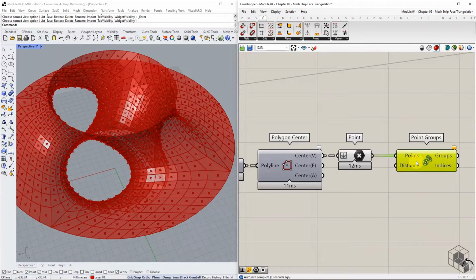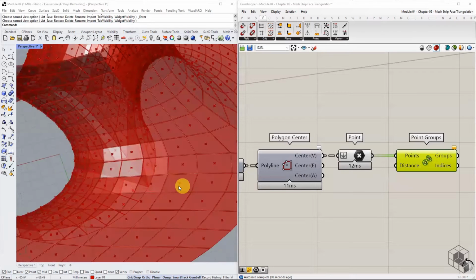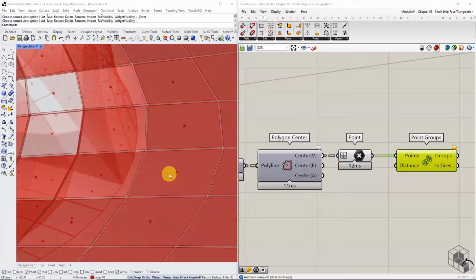This distance threshold is carefully chosen to be small enough to form pairs and large enough to avoid groups with only single points. Since these are almost identical quads separated by 0.5 mm, we can set the distance threshold to 5 times the material thickness, 2.5 mm.